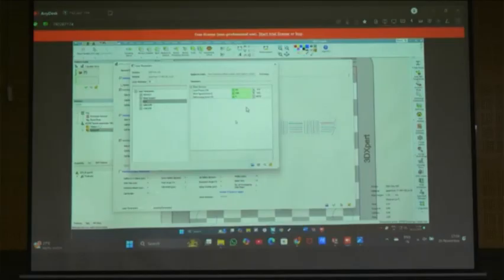That is how I did my research too. The geometry we use is some cube samples. While doing the optimization, everyone prints cubical samples, 5 by 5 by 5 or 10 by 10 by 5, only 5 mm or 2 mm height. They print them, test the relative density using the Archimedes principle, and do the microstructure and everything. Using the Archimedes relative density, they find the porosity, external porosity.